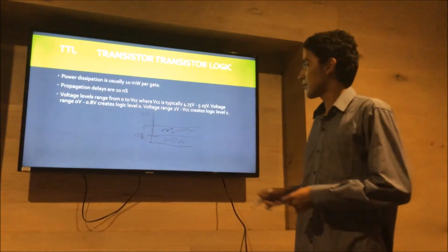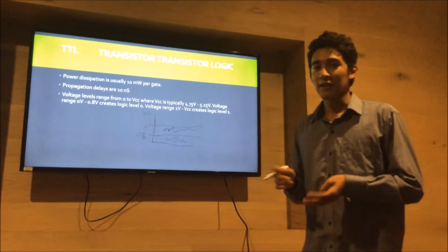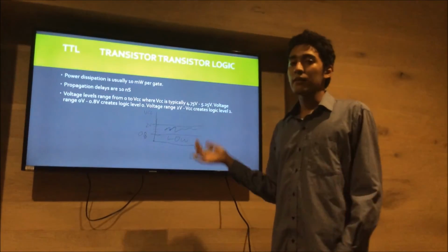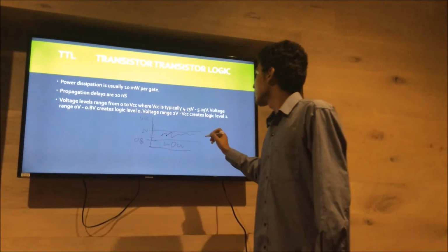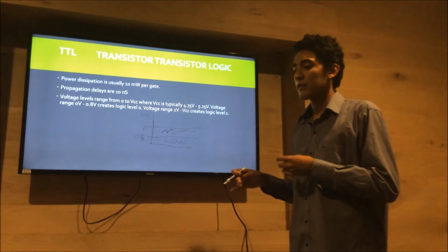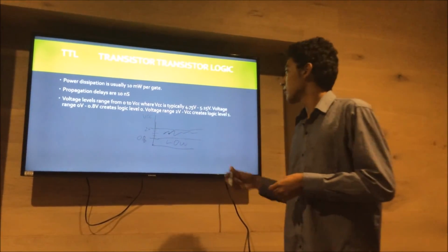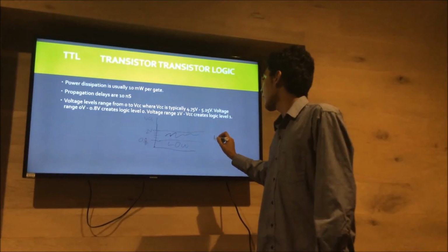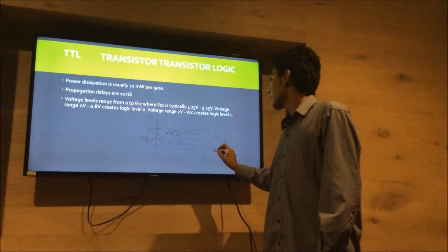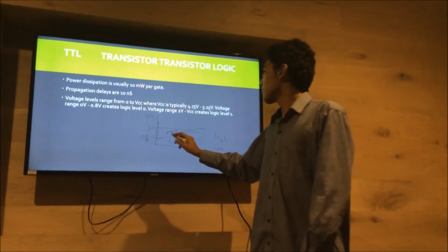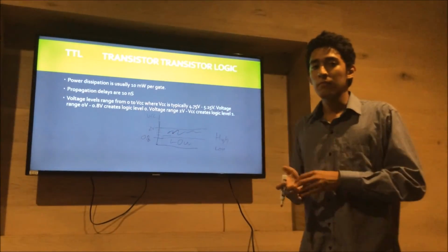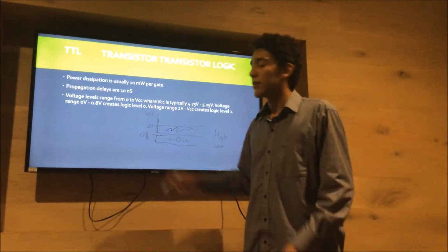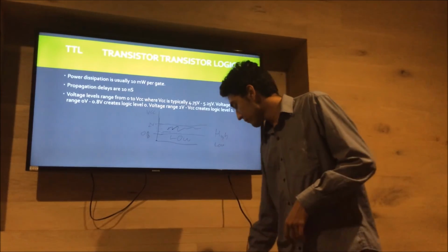That region is called the prohibited band, and we're not talking about dangerous voltages or something like that. It means that the integrated circuit doesn't know exactly what value to deliver at the output, so it will be randomized. It can be high or low. It depends on where the region is more focused. But for that reason, we have to be very careful with the voltage applied to the inputs.